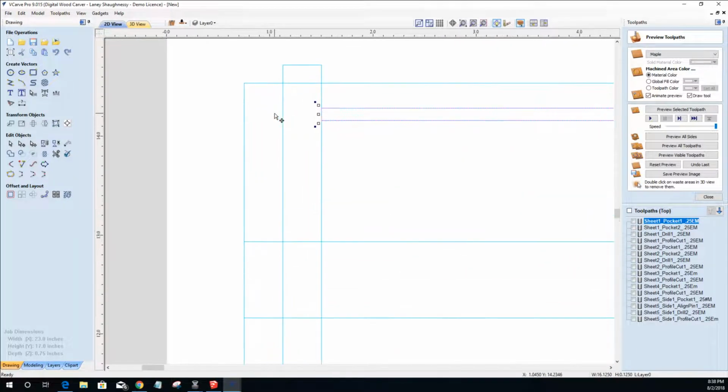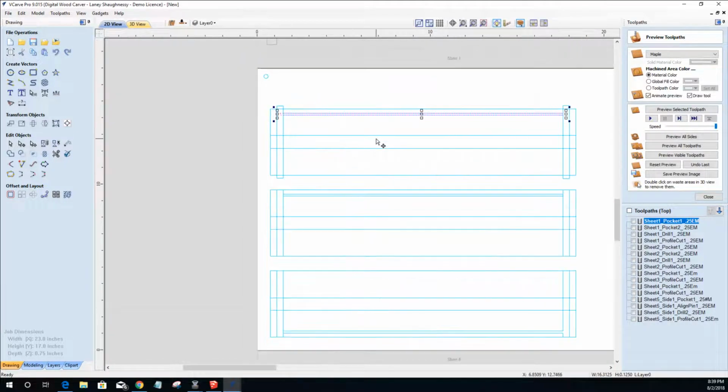Now this one is only going to extend out into this dado groove. All I need to do is clear this line when the router bit's cutting. So I'm not going to drag this all the way out here because this part doesn't get cut. I'm going to drag it out in this opening where the router bit has cleared out this pocket here. So when it's cutting this out, it's going to be air here. So I want to keep that.